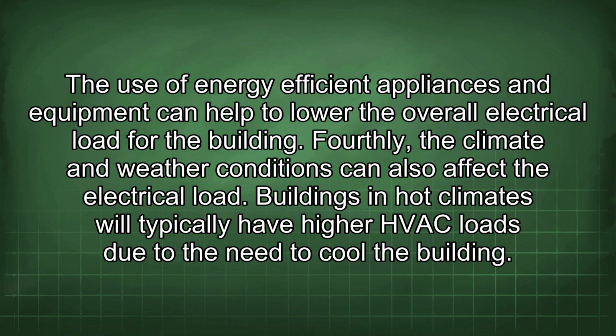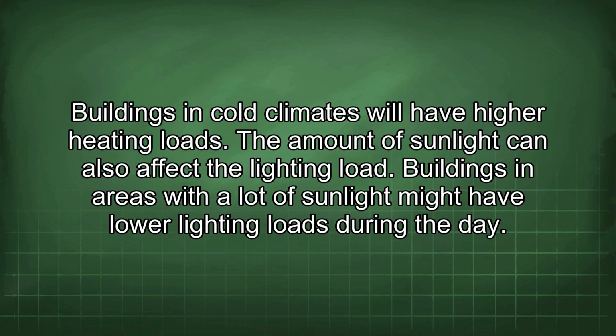Fourthly, the climate and weather conditions can also affect the electrical load. Buildings in hot climates will typically have higher HVAC loads due to the need to cool the building. Buildings in cold climates will have higher heating loads. The amount of sunlight can also affect the lighting load. Buildings in areas with a lot of sunlight might have lower lighting loads during the day.